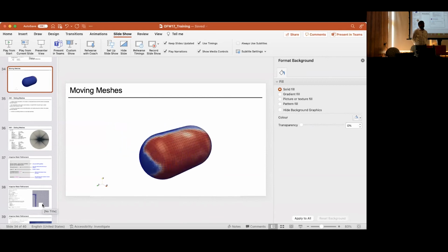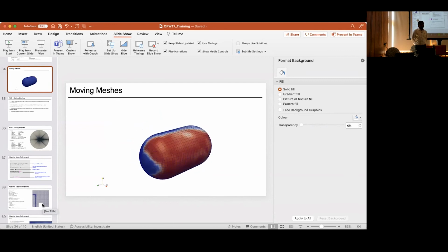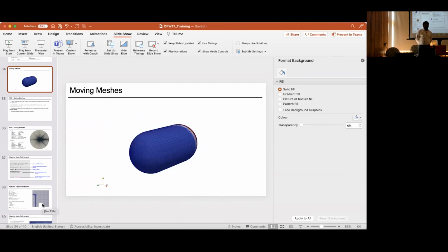But is there any advantage to simulating the motion of the entire domain? Yes, because let's say your body is flexible. I'm just thinking aloud. Correct me if I'm wrong. If your body is flexible and you want to simulate the FSI sloshing dynamics within the body, I think by imposing velocity it would be difficult. But if you use a coupled solver and use this whole move mesh approach, it might be easier.